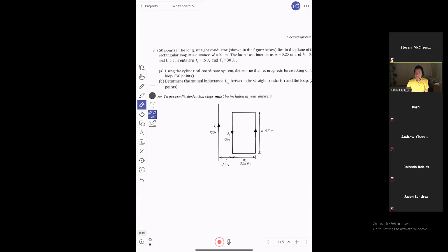So now the flux density, we know the flux density produced by this guy. So what I have to do is simply, the mutual inductance is how much flux generated by this I1 is captured by this second circuit. Well, basically sum up all the flux density across this area, and divide by the current over here. That will be your mutual inductance. Any questions? The general idea. Okay, so let me solve that.